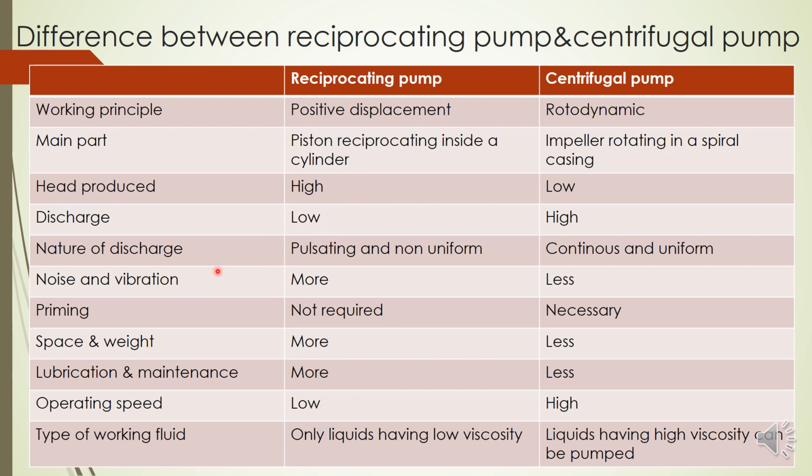Discharge is low, discharge is non-uniform, noise and vibration is more, space and weight required is more, maintenance and lubrication more, operating speed very low. So most of them are advantages of centrifugal pump. That is why we are preferring centrifugal pump over reciprocating pump in most of the applications.